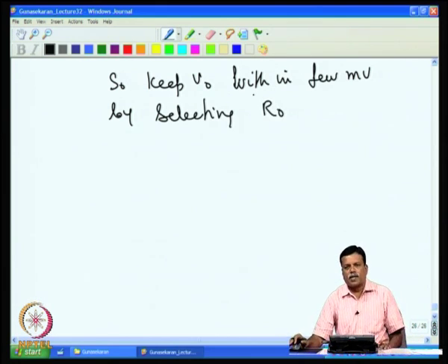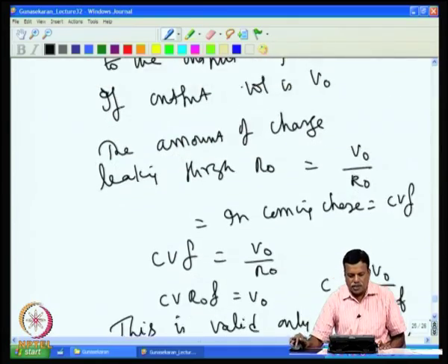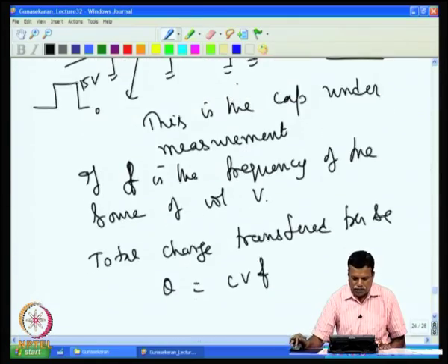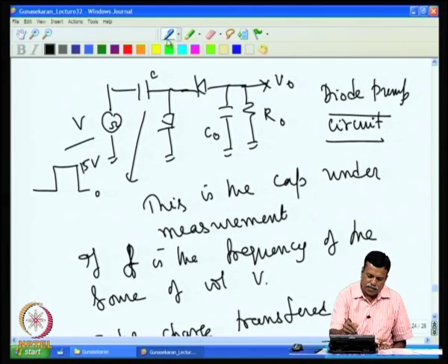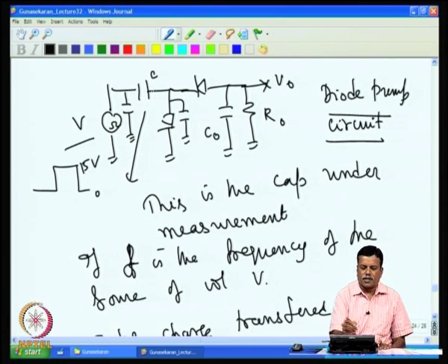So, this error is there, plus there are also other errors, because the diode is conducting. And if you have a capacitance at the other end, for example, a capacitance from here to ground, it is charged and discharged through this one only.